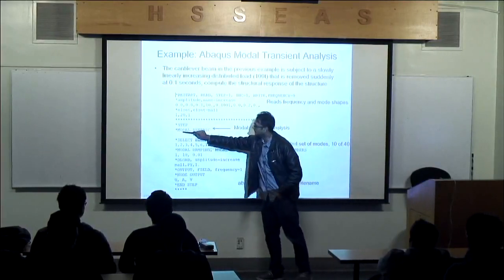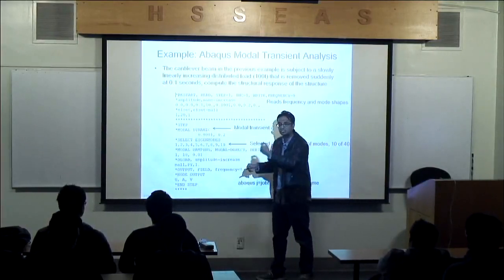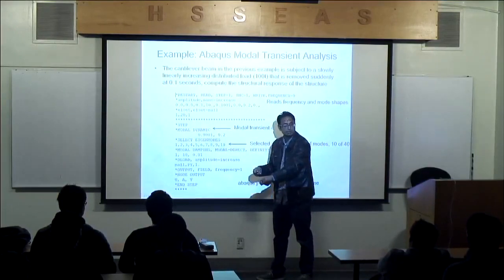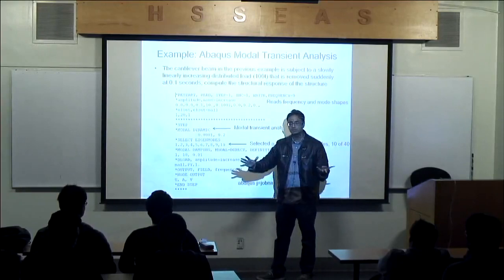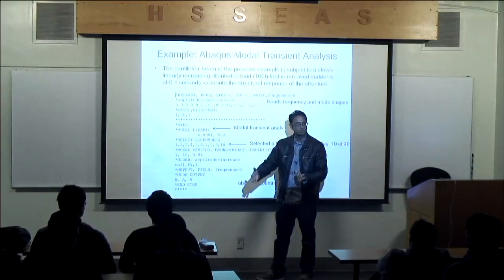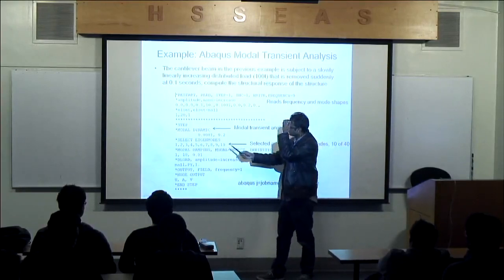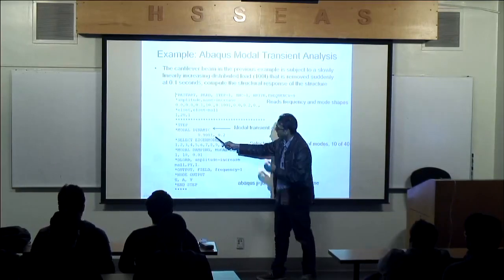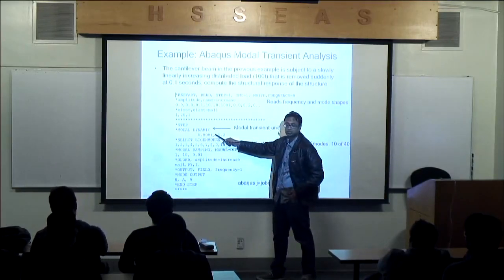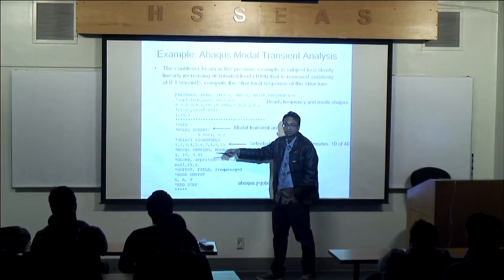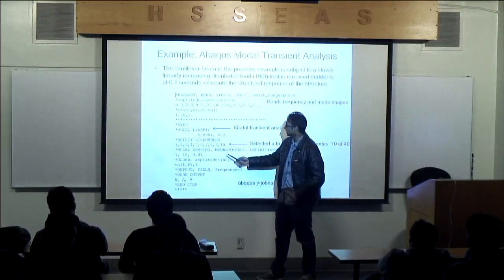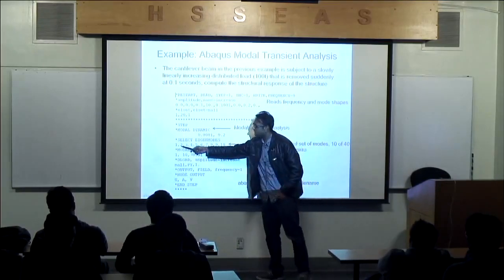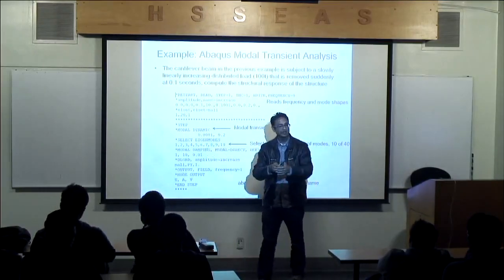If you put start modal dynamic, that's going to initiate this transient modal analysis we're talking about. It's going to do this decoupling we're talking about. It's going to do all these steps for you, plus Newmark beta and all that. And so I'm solving every 1e minus 5. I can do that, and it runs really quick because, again, these are all decoupled. I selected how many eigenmodes I want to include. Remember, we talked about I can include as many as I want.